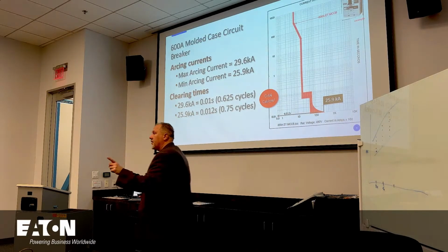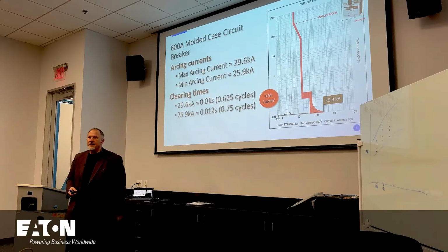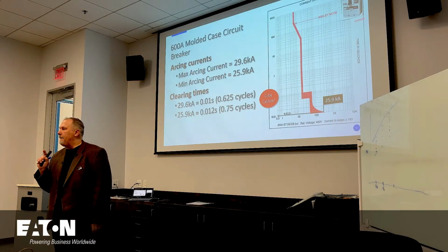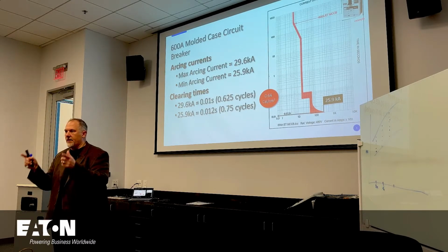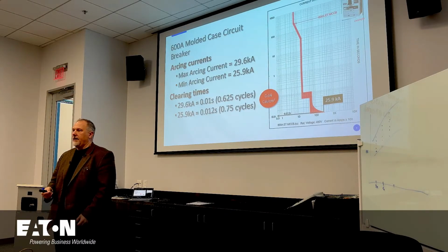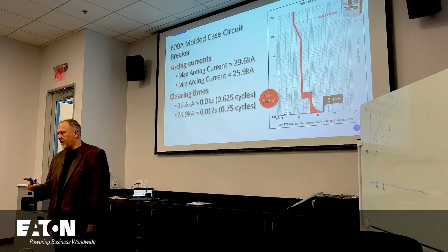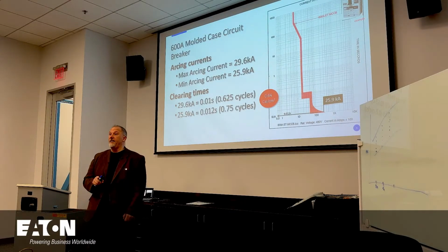Now, all I'm going to do is change the breaker to an insulated case. Now, insulated case is really a molded case circuit breaker. Insulated case circuit breaker is a marketing term. It has nothing to do with codes and standards or engineering, period. It is a marketing term that the industry recognizes. Just like I fight this with my resi people. They'll say, I have a load center. I'll say, okay, well, you've got to go to UL 67 for panelboards. No, it's not a panelboard, it's a load center. Marketing term. Okay, insulated case circuit breaker, UL 489 device.